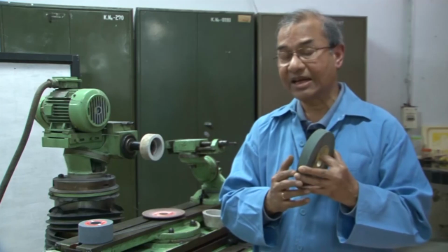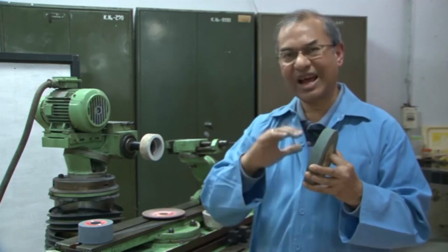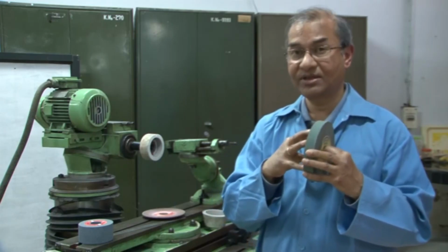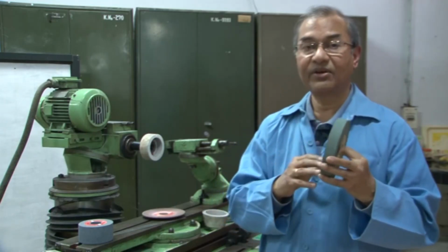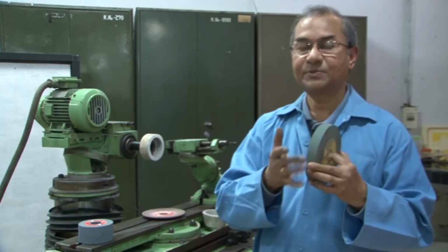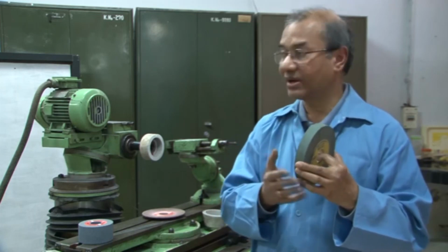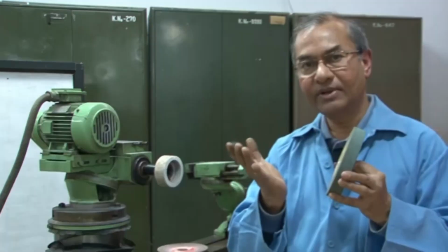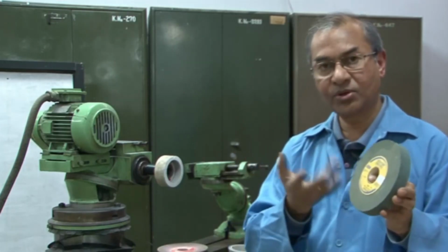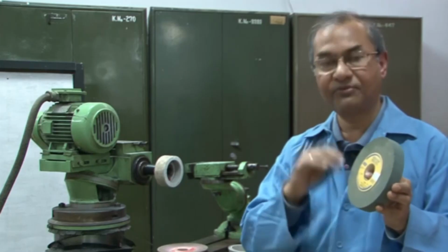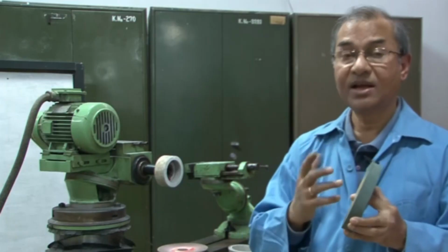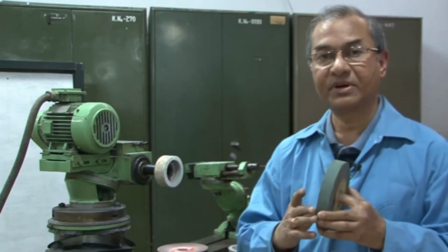All right. In that case, you have to be very sure that the temperature rise is not much, and since in grinding the grinding velocity is very high, which is 10 to 80 meter per second, you can understand that it is a very high speed, and at that speed the temperature will be very high. Even you will see here that when the grinding process is on, there will be chips which are so small, and they will be flying away in terms of sparks. You can see the sparks, they are actually burning. Temperature may go up to 1500 degrees centigrade.